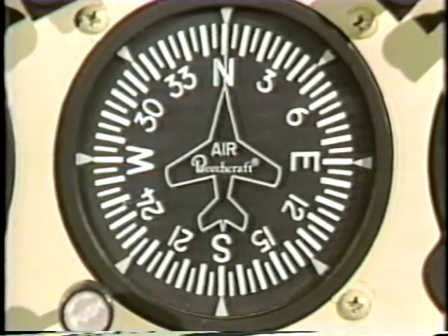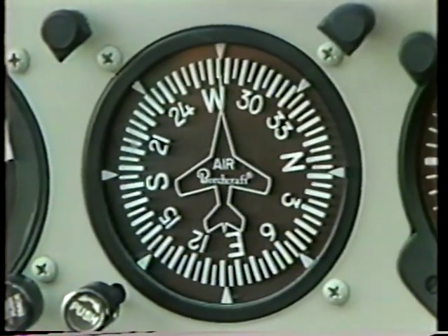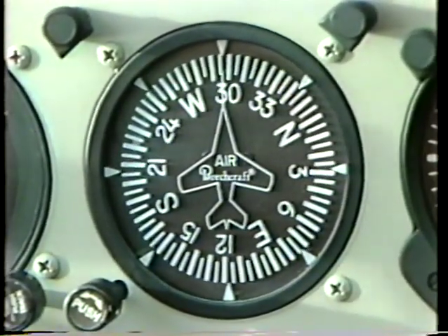The heading indicator is used in conjunction with the magnetic compass and is periodically checked with and set to the compass reading. We use a gyroscopic heading indicator during flight to maintain headings, to facilitate reading heading information during turns, or while in rough air. The heading indicator, like the attitude indicator, is usually an air-powered gyro that uses the principle of rigidity in space to maintain stability. As the instrument case and the airplane revolve around the vertical axis, the card provides clear and accurate heading information.